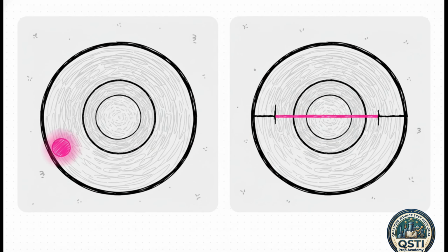Now, depending on your facility's setup, you're going to run into two main flavors of these systems. Point CEMS measure gas concentration either at a single, specific point or along a really short path, specifically equal to or less than 10% of the stack's equivalent diameter. On the flip side, path CEMS are measuring along a path greater than 10% of that diameter. Why does this matter? Well, it literally dictates precisely how and where you're allowed to measure within that exhaust stack.